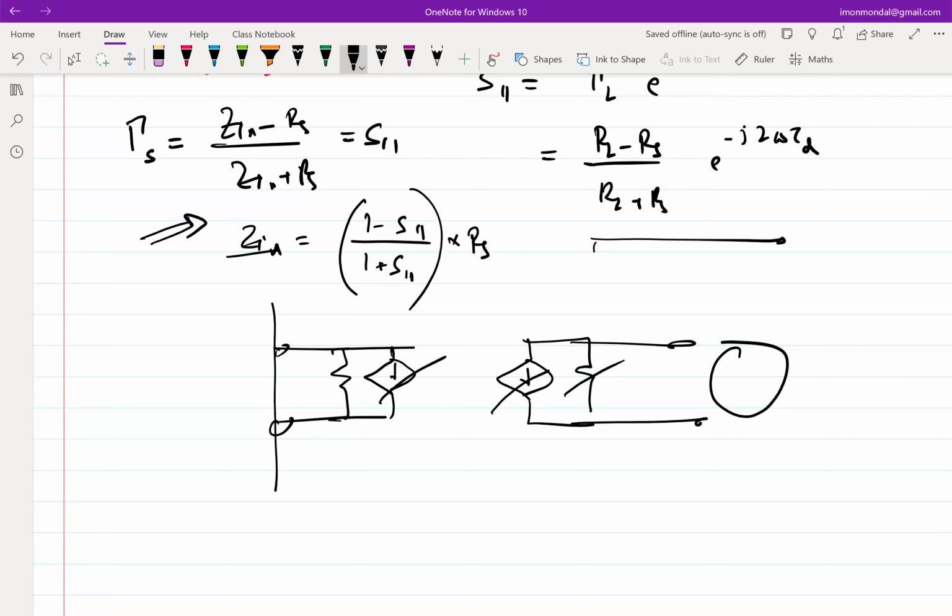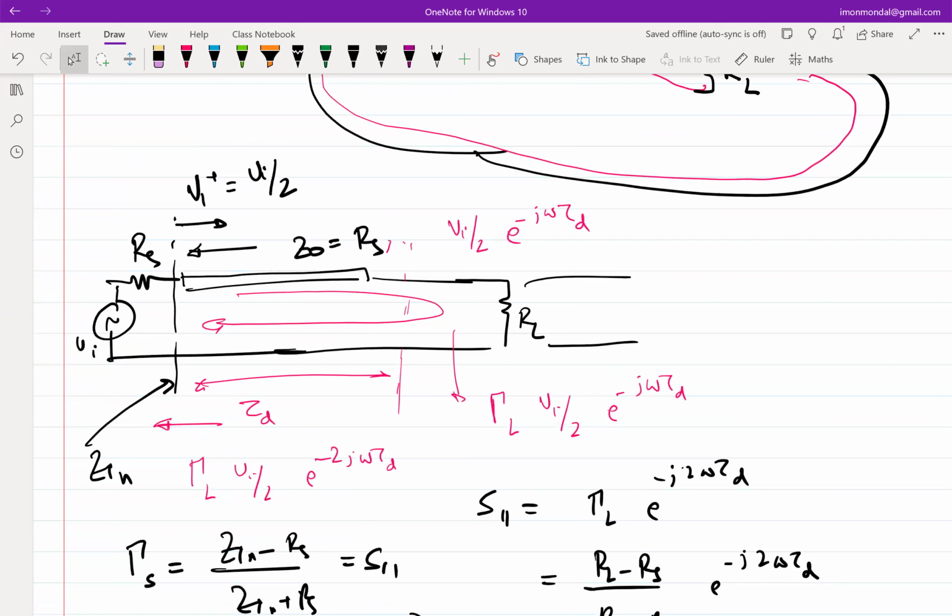Ideally here, but you cannot take it here because you cannot connect the device just where the VNA ends or begins. So obviously you need that long wire. The whole purpose of generating this S11 framework was because you cannot do away with that long wire. If I could have done away with the long wire, I would have directly used Z parameters or Y parameters. S parameters would not be required. Anything with 2 is not of concern. Yes, only S11 is of concern then.